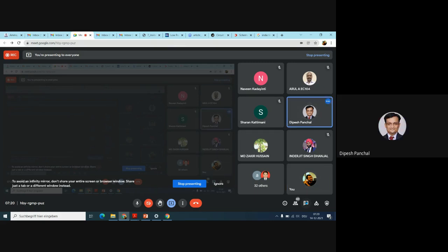Anyone else? And sir, the BJT you mentioned, is it only parasitic, not a separate device like a MOS? No, it is a separate device, but if you go into the foundry model files, you'll find the BJTs, and those BJTs are parasitic BJTs.